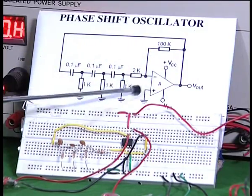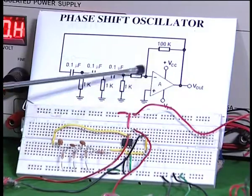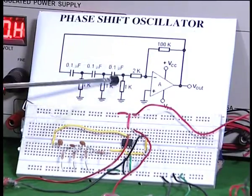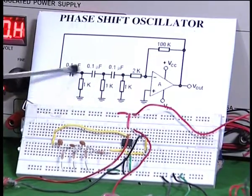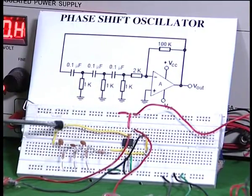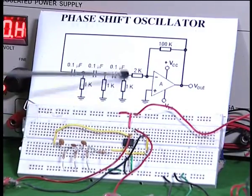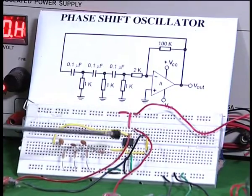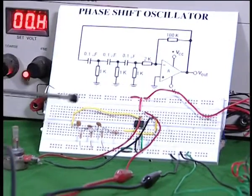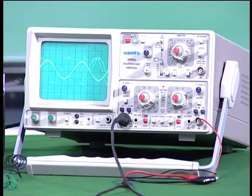So, this is an inverting amplifier because you are connecting to the minus input. It is an inverting amplifier, therefore, there is a 180-degree phase shift here. That output I take and give it to a series of 3 RC. They are all 0.1 microfarad, 1K equal values. You can see in the circuit here 3 1K resistors and 3 0.1 microfarads here, and that output is connected to the input pin number 2 of the operational amplifier. And for the feedback resistor, I have used a potentiometer, carbon resistor here, and the output is monitored using the oscilloscope.